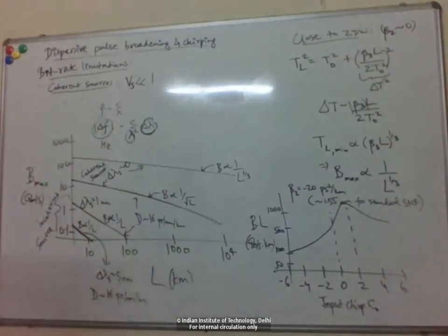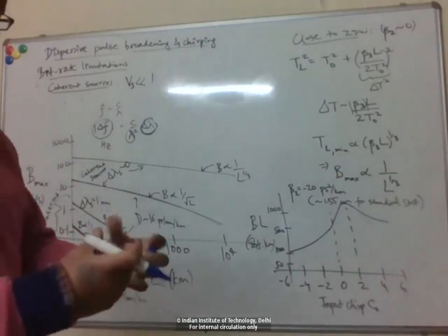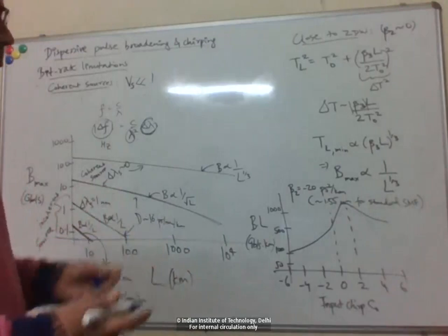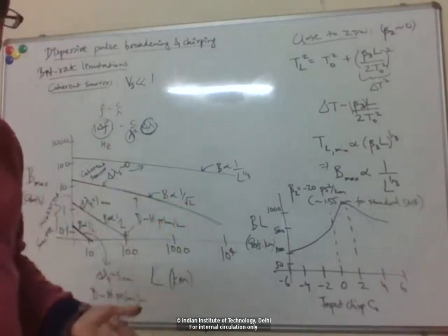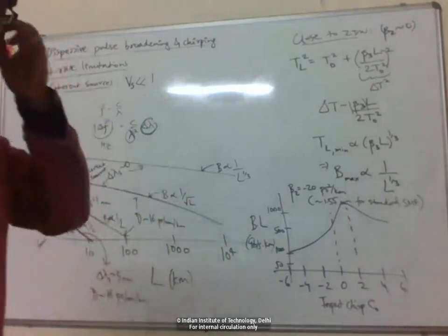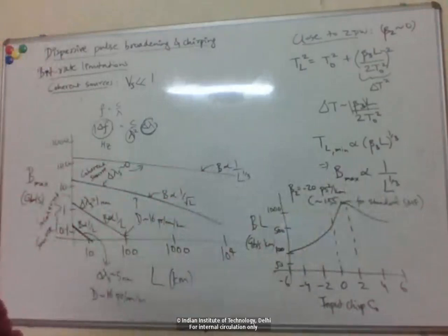And sir, one more question. Is link length all the optics, including the transmitter and receiver part? So what exactly is link length? It's just the fiber length, right? Because the transmitter is just a chip, a laser with fiber attached, and the receiver is also just a photodetector on a chip. So optical link and link length are both the same thing, sir. Yes, so link length is basically just the fiber length, the effective fiber length.